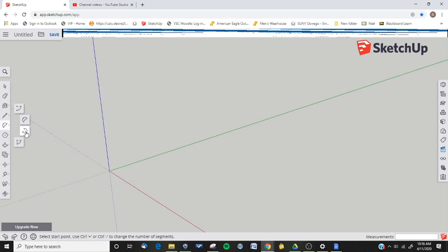Moving on, 3-point arc. Same thing. Right from the definition, this tool enables you to draw an open arc based on a pivot point. So what we're looking at is we start here, come down, and again you can define what you're doing here by angle and length depending on which part of this function you're at. So let's start that again. So start, length, there, and that becomes your pivot. So you can, again, move in multiple directions, and this one allows you to do some pretty unique things.